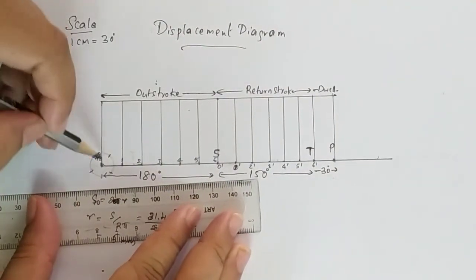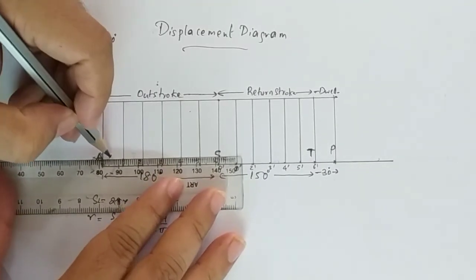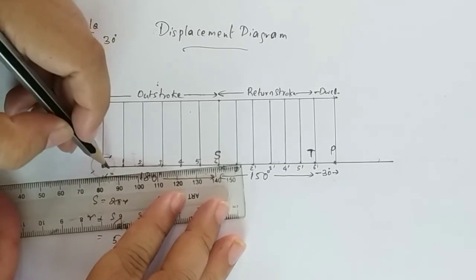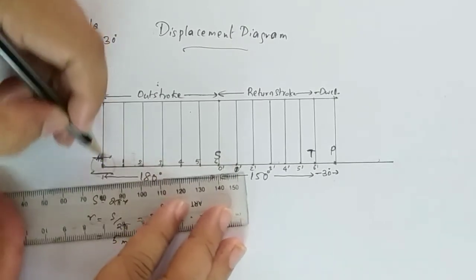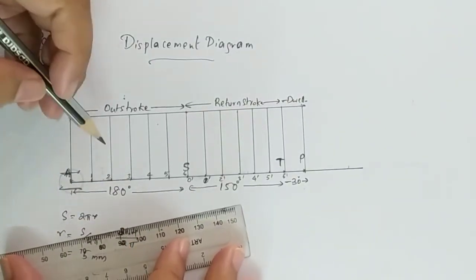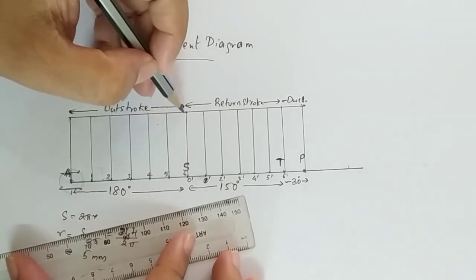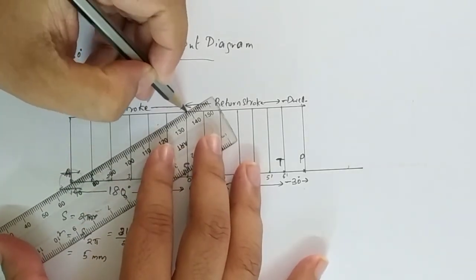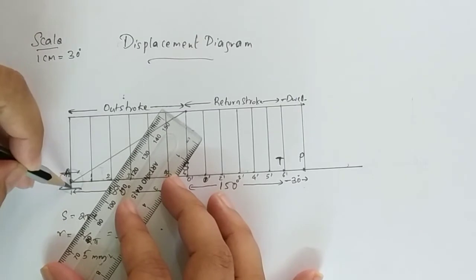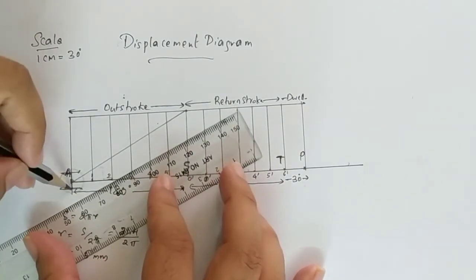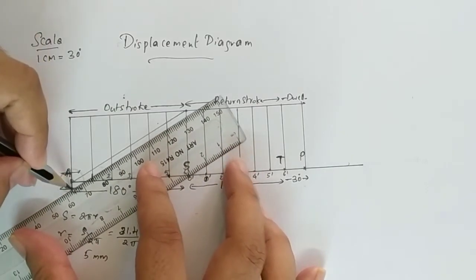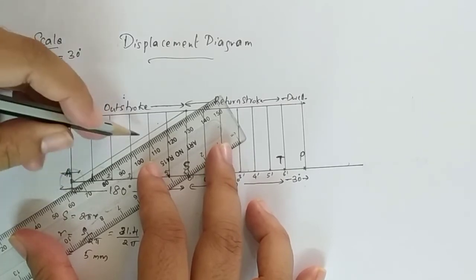After dividing this into 6 equal parts, you can join those points with horizontal lines. Since you already have this line here, just keep it like that. Keep in mind this line should be a horizontal line. Now from the center you join this center. Then from the lowermost point, where this vertical line meets the below line, from that point draw a line which is parallel to the above line.